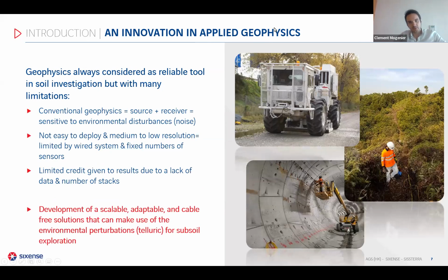Of course, to complete those site investigation works, conventional geophysics is currently applied, or has been applied widely, for infrastructure projects. The main thing about conventional geophysics is that it requires installing sensors, laying cables on the ground, sometimes using seismic trucks. That is not easy to deploy in city centers. It's not really accepted by third parties.